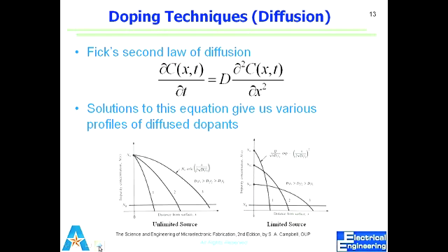These two cases are very important. If I have a diffusion where I want to restrain the dopants, but I want them to go deep, there's a different recipe. But if I want to have a gradual change and I want to have as much dopant as I want, there's a different recipe for that. And the second law of diffusion now defines it in respect to the concentration itself, with respect to the distance within the substrate. We'll look at these more closely once we get there.